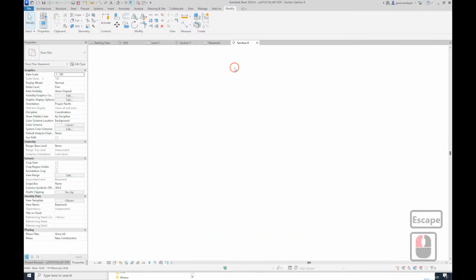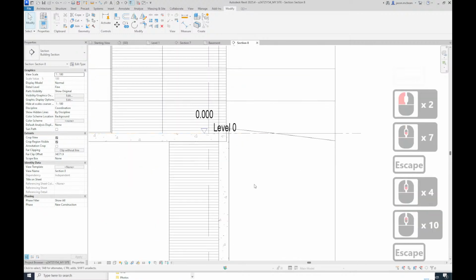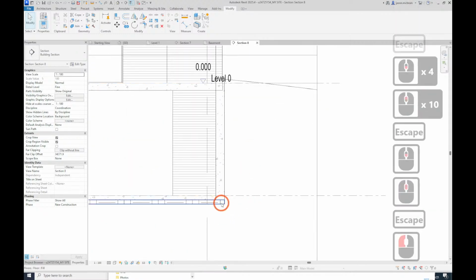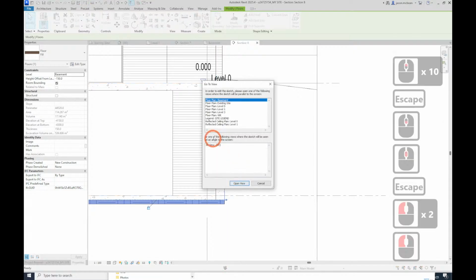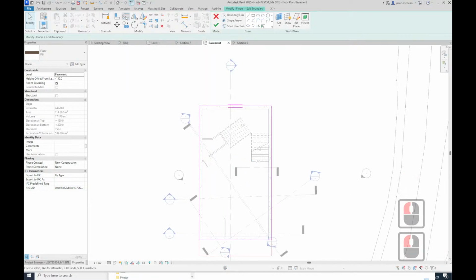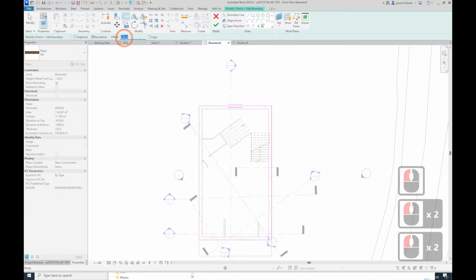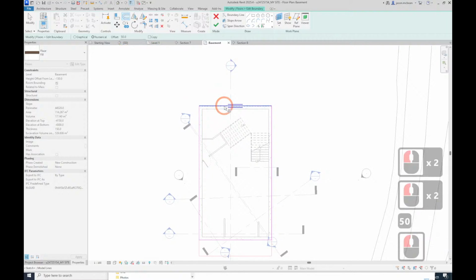But what I noticed with your model, it's got a bit of a cavity. So I just made this slightly bigger, and then that excavates it. So then, very quick, offset. Give it a value. Let's make it 50 mil. Is it 50 mil offset again? Yeah, it's 50 mil.